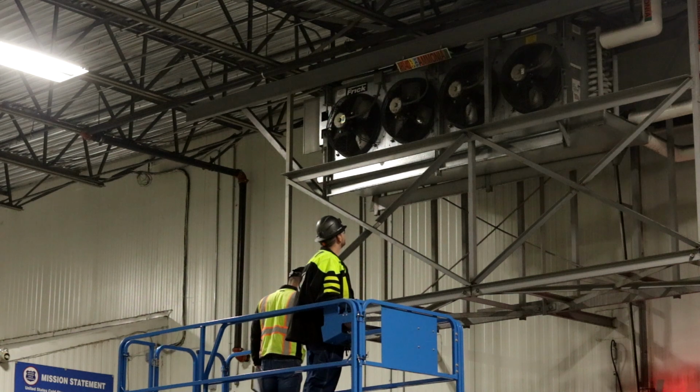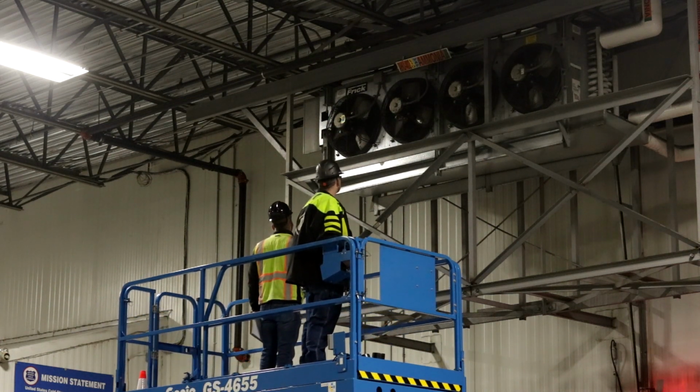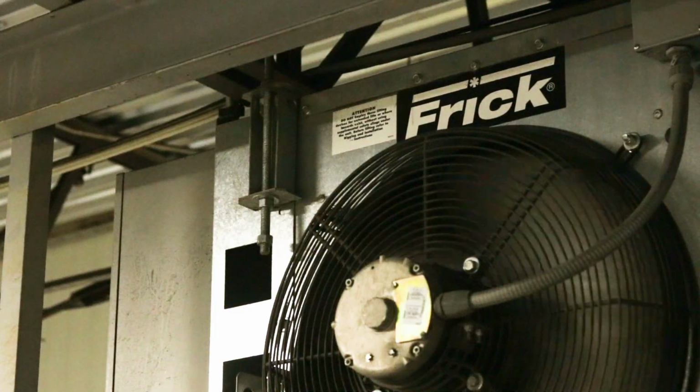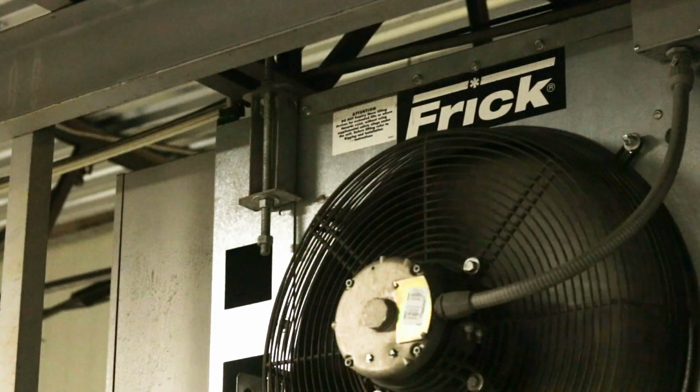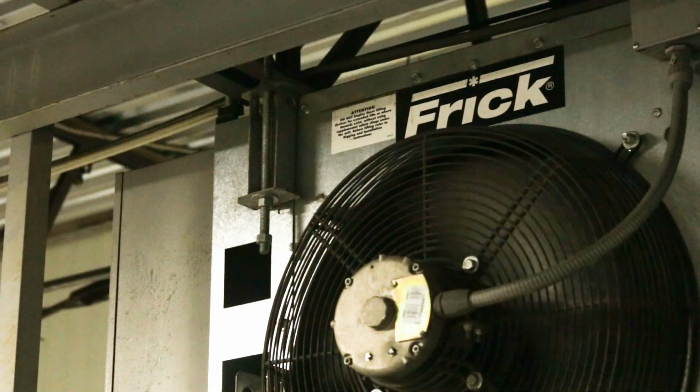The most common type of evaporator is an air cooling evaporator. Air cooling evaporators are designed to absorb heat from the air to reduce the temperature within a space. In most refrigeration applications, the air is actually a secondary coolant that is then circulated by fans to cool something